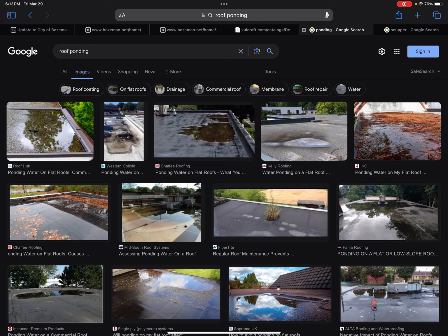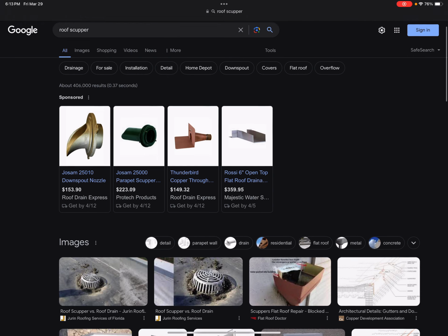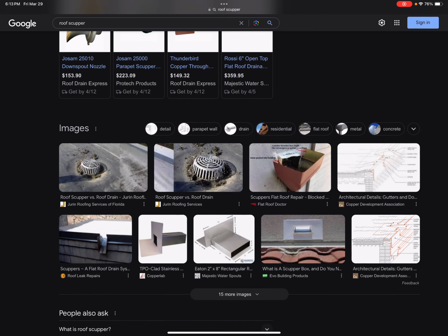Once you understand the rain intensity and the geometry of your structure, there really is a requirement to understand the draining system for your roof. And so, really any roof system, the International Building Code requires there to be a primary and secondary draining system for every flat roof. And so, I'm not sure how many of you have been on a flat roof before,